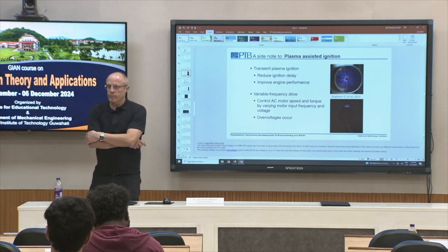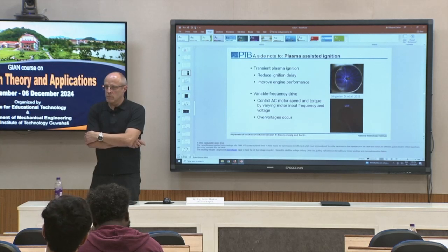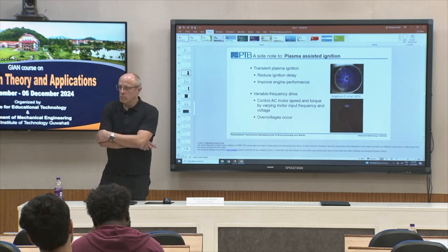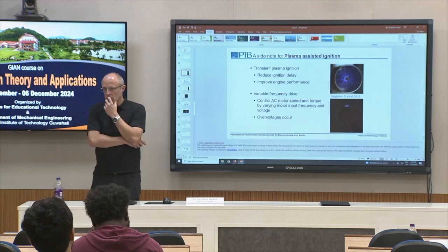Pressure rise happens because of two reasons in SI engine combustion. It's because of the change in volume: when the piston moves, volume changes and pressure rises, and again because of combustion. So we have to filter out these two separately and identify at what point exactly combustion happens, looking into the pressure rise data. So how to separate those two things?